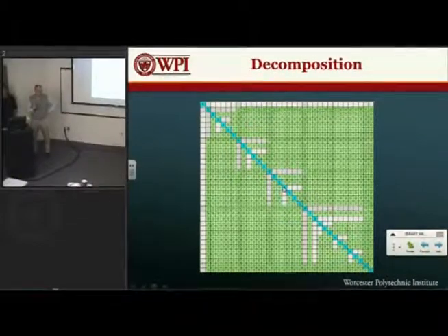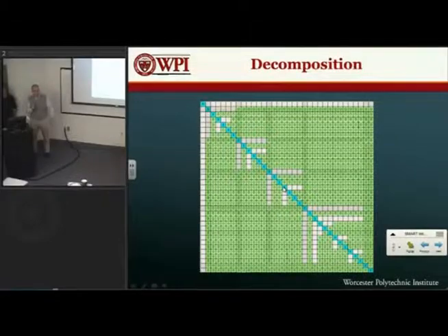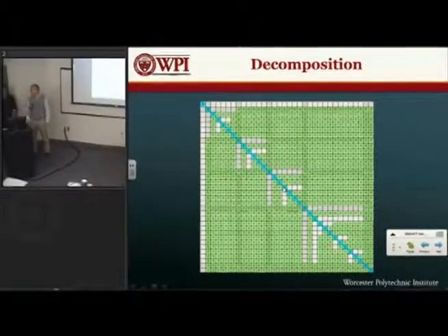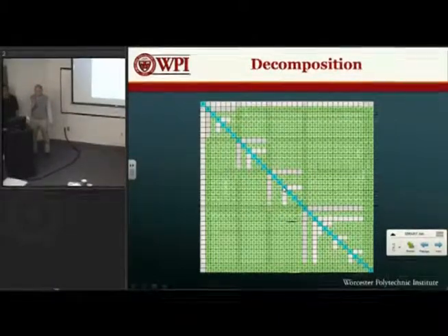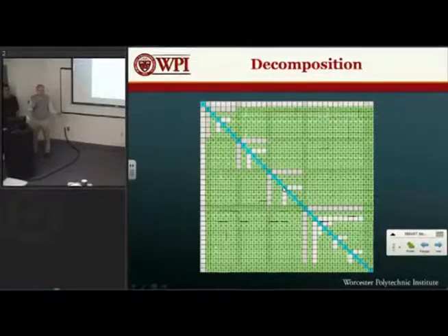A classic case is a rolling mill or extrusion, because if you get a power outage, all the material is moving through at very high speeds, and the rolling mill has a bunch of momentum. If the rollers stop, it goes all over the place, and you spend weeks with a torch cutting it out. Same thing for some of the continuous casting operations. So there are some places where you might have an FR to provide backup power, but for the most part, power is reliable enough, but it's something to think about. We seldom have an FR that's to supply oxygen for the operator, right? We assume that's going to be there.